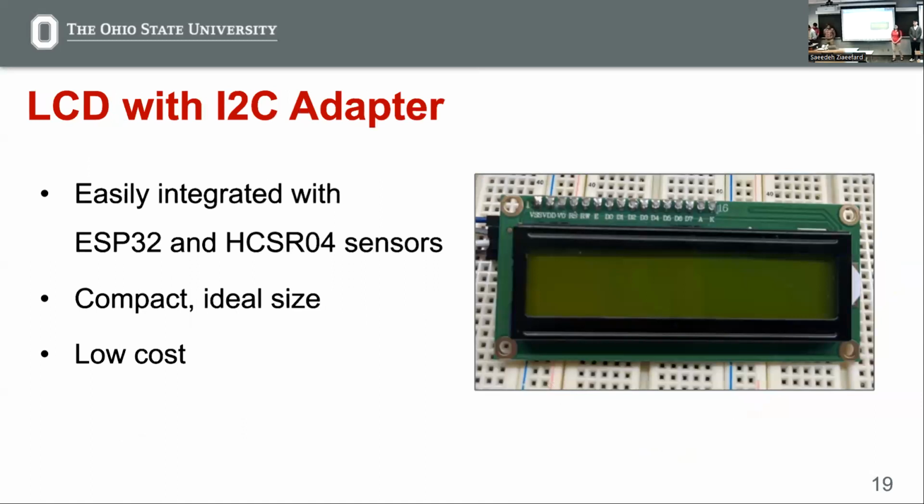So we decided to use the LCD with the I2C adapter, and the reason for this is because that helped to simplify it when we're integrating it with ESP32 and HC-SR04 sensors. It helped create a 4-pin connection, which was really nice for us.